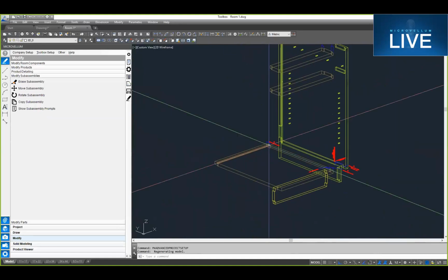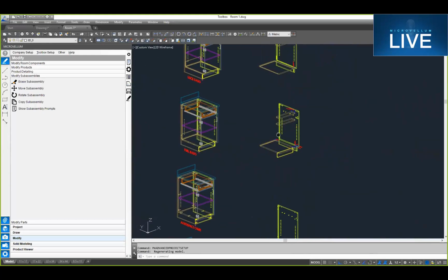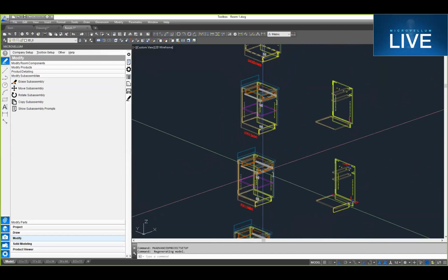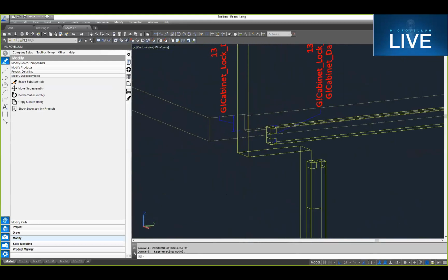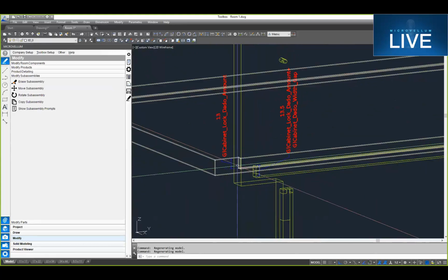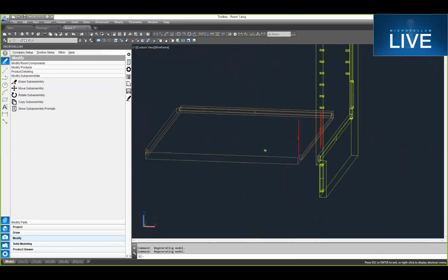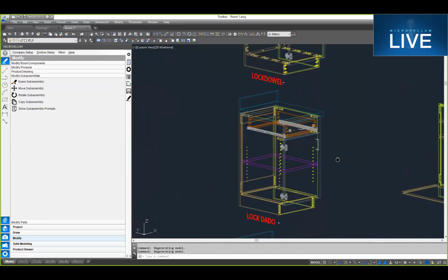And so depending on how you want to construct that, you have full control over exactly how you want that dado constructed, where you want your nips, and how you want that set up and machined. And so for a lock dado, I've just got a dimension as far as how deep I'm machining that, and so the thickness of the dado itself, and then again, same thing, I've got that gap, and so that's going to give me the size for my groove with my stop dados and all that info on there as well. So that's how I would configure my dado construction there.